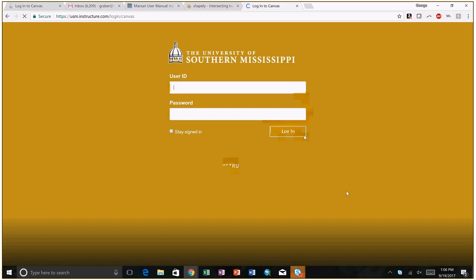So basically, it's like field digitization. I used that concept before. Instead of you drawing it on your screen, you're standing in the field, physically digitizing a path or a point or some object. So it gets used a lot in that capacity. I mentioned earlier using a prism and a rod to get the location from a particular object.